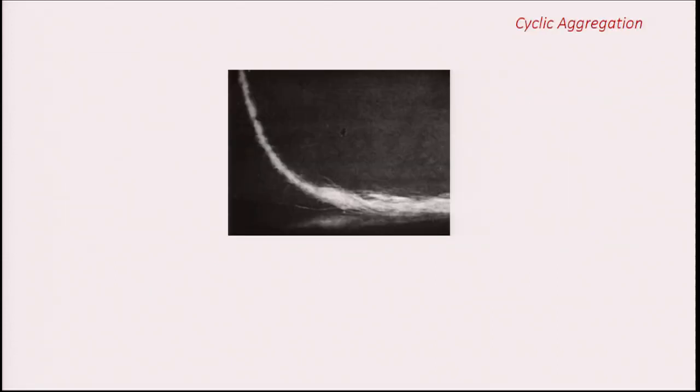Now, this high speed camera image clearly shows what is happening at the rotor wall. The peel off point is shown here. The rotating arm of the yarn meets the fibers which are collected at the rotor groove. In this case, it is very clear the twist is flowing only up to the peel off point. Let us say the peel off point is the one where the arm and the fibers collected on the rotor groove meet.